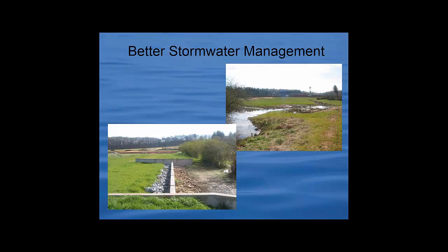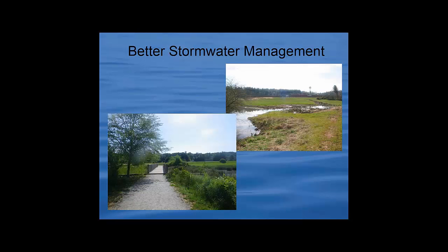We broke the connection between those hard surfaces and the stream, and that's a lot of what green infrastructure is all about in a small community and in large communities: getting away from the traditional collect and convey directly to receiving waters, and allowing that water to infiltrate or evapotranspirate back into the atmosphere. There's just a low head dam with these weir notches that you see cut in here, and subsequently that area has been developed. This is on city property, into a city greenway.